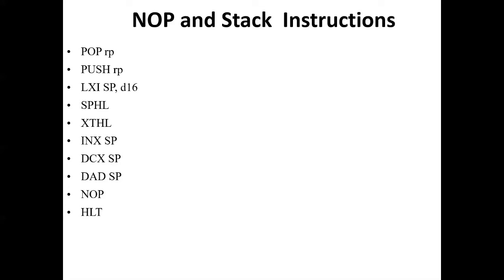Next is INX SP. INX SP instruction is a special case of INX RP. INX SP instruction is used to increment the SP contents by 1. It occupies only 1 byte in memory. Now suppose SP had the value FC00H, then after executing INX SP, SP becomes FC01H.